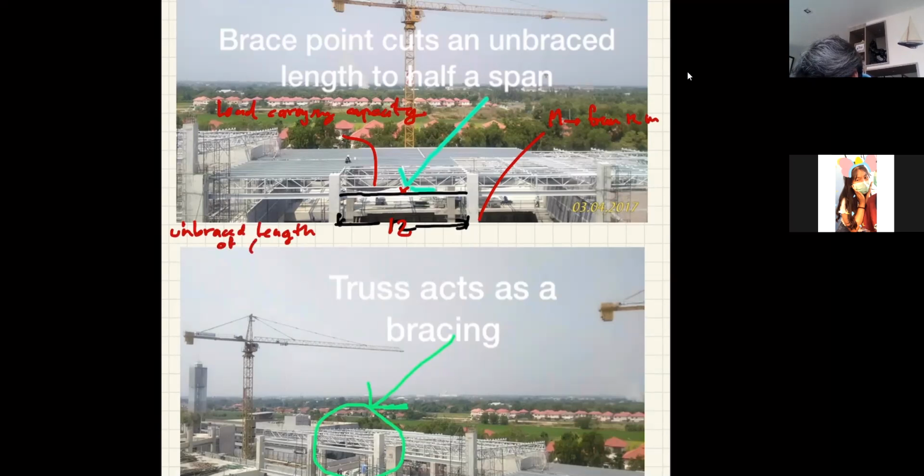We don't consider the unbraced length equal to 12 meters. Our unbraced length will be 6 meters, and that's how we can calculate the flexural capacity of this beam.